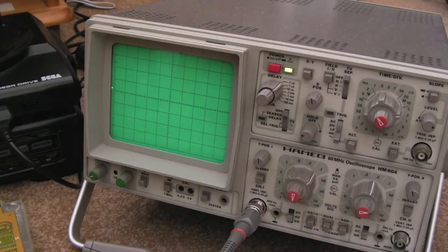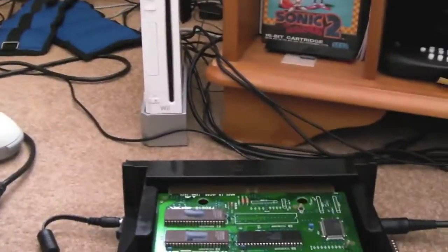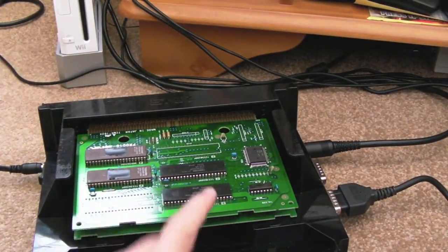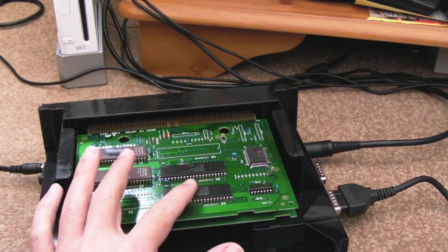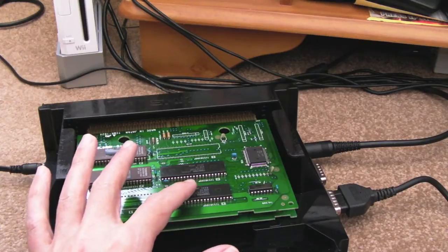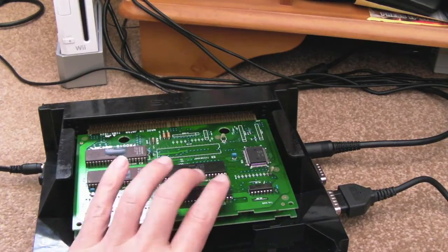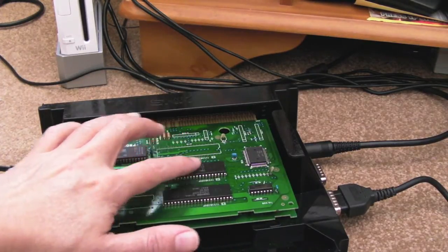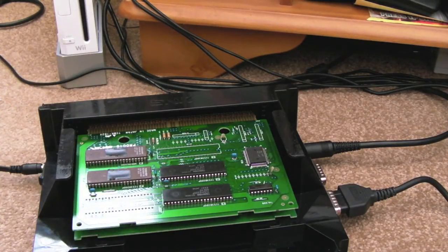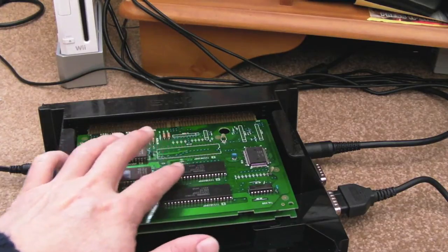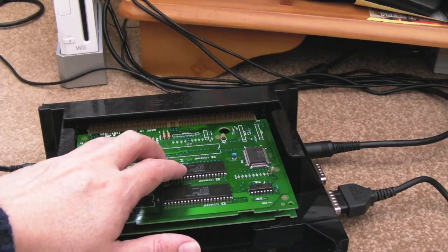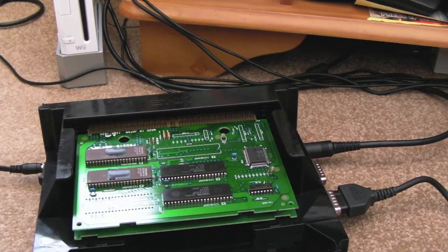So, like I say, make of that what you will, but effectively that was the one I did first, where some of the transitions were not right, and pretty much on every other pin, it was bizarre. It's quite a few of them, and they're not in numerical order, so there's no pattern there. I think quite a few of them have gone. And then when I did the second one, we got some really unusual readings. It looked like there was some noise on there as well. So that chip is acting very strange. I think that could be the one that's causing the problem here. So I'm going to replace this chip first. Let's see how we get on with that.